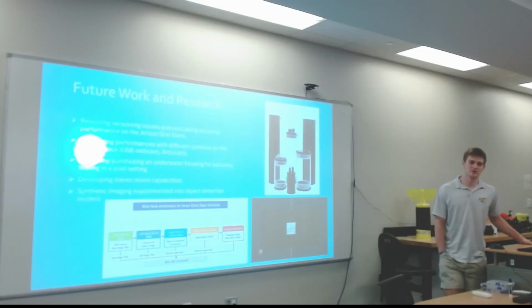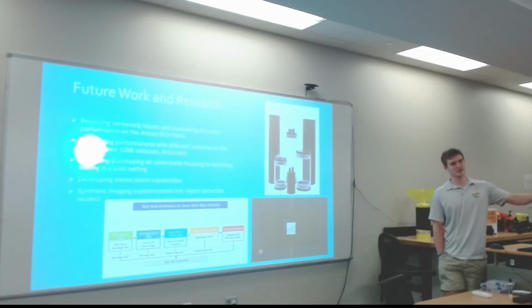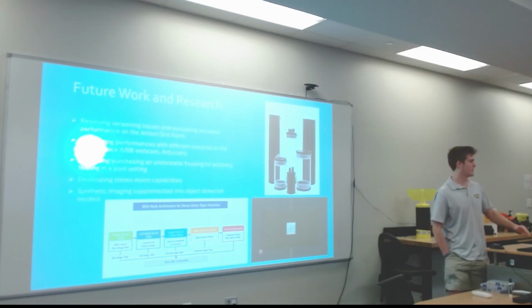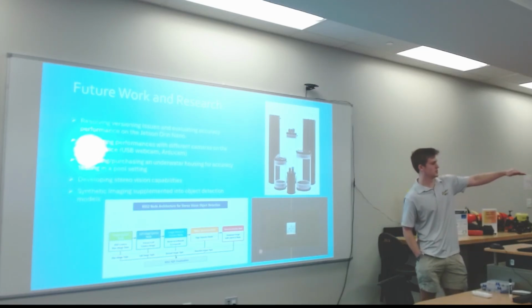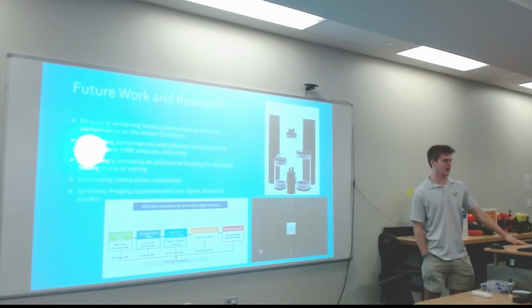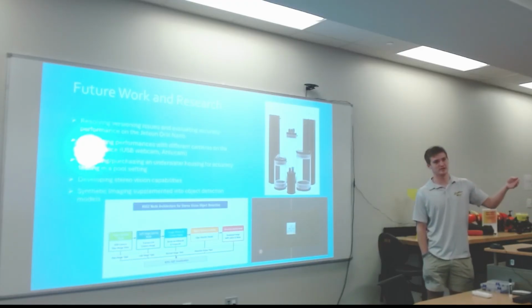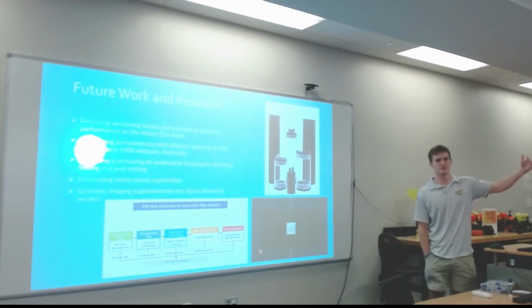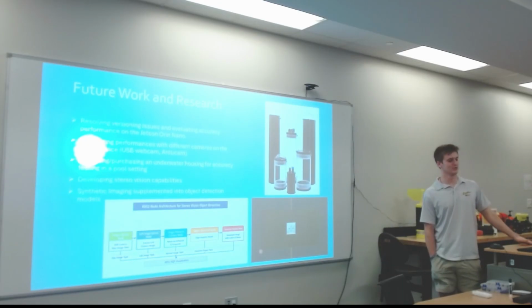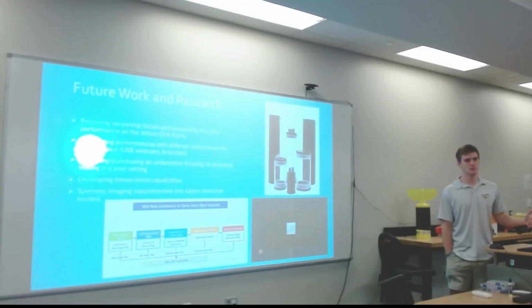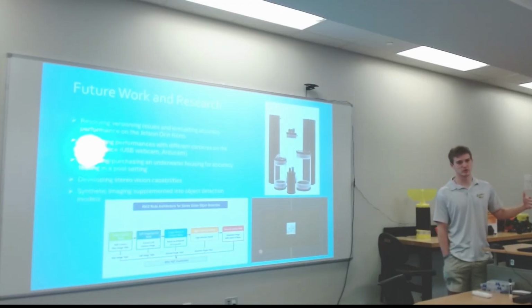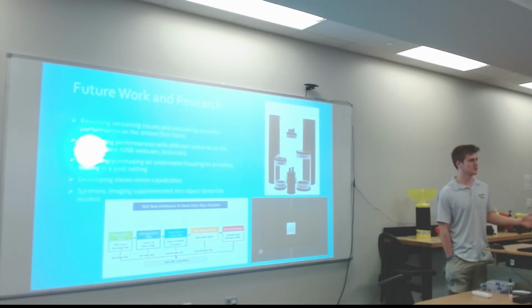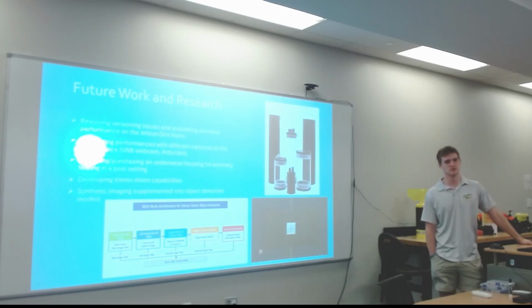Yeah, so I did do some of the research. I couldn't put it in the presentation, I didn't have time, but on the actual roll of the camera, just adjusting that mount left and right, I actually found that slightly shifting that, I mean like 5 degrees or so, can make it drop from 99% to 0% accuracy, so it can have a huge effect on it. So that'll be a big part of the AUV. One, getting a model that's less volatile with all that, but also making sure your gyroscopic system is keeping that AUV as stable as possible.